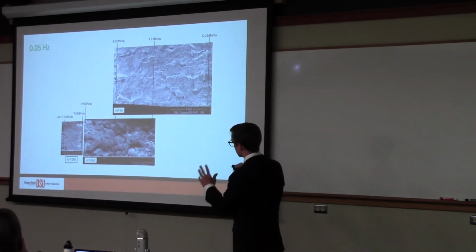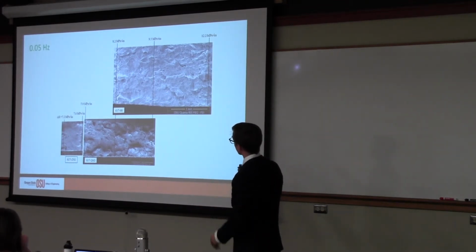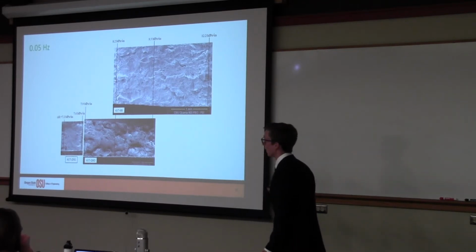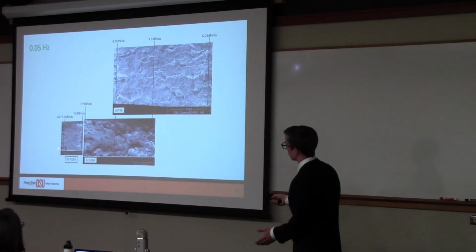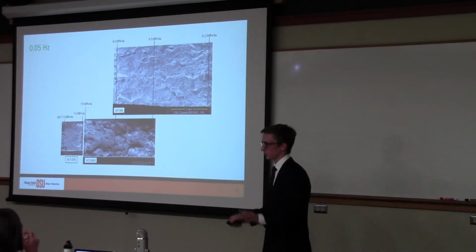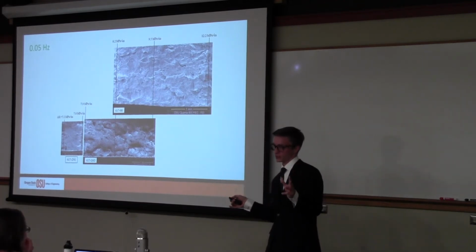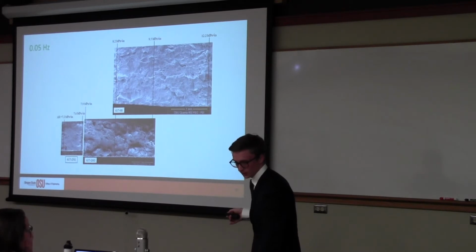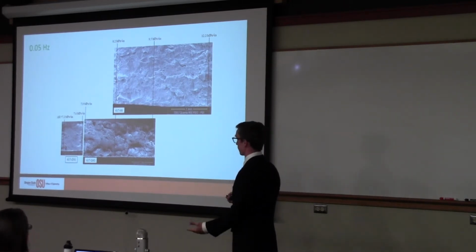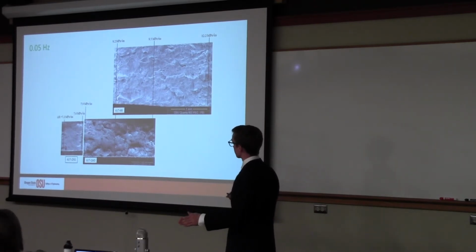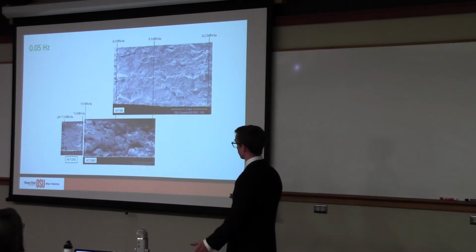And it's interesting to contrast these three in particular because these are different sample geometries. This sample is a little bit thicker than these two samples. So the thinner samples seem to have even more roughness at lower delta K values. And that's interesting in and of itself. And we have what appears to be a thickness effect going on with our samples. And we've got to grapple with that and what it means for the study of fracture mechanics at these high temperatures. Not a main point of our study, just something that is interesting that is going to be relevant for future work.